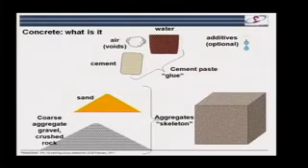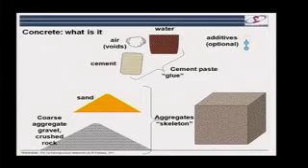You see, we start with cement, of course, and we mix the cement with water, and this gives us what we call cement paste, which is basically the glue. And this glue glues together the aggregates, which we can think of as kind of the skeleton of the concrete. And here, as I will explain, we have different sizes of aggregate. It's very important, this aspect of having different sizes. We go from sand, which is the fine aggregate, through to bigger and bigger rocks, which can be either gravel or crushed rocks. It says here additives optional.